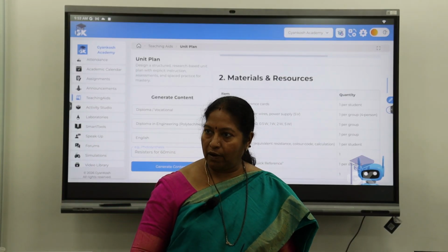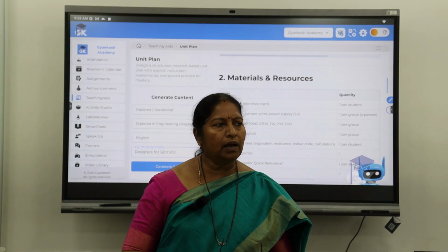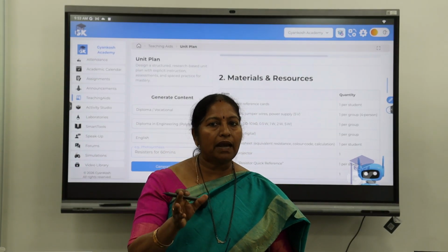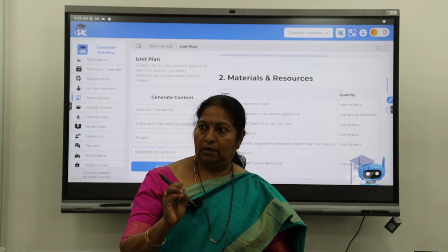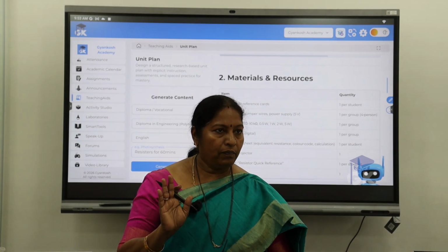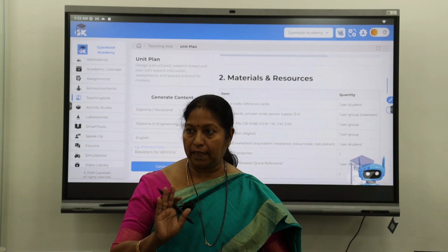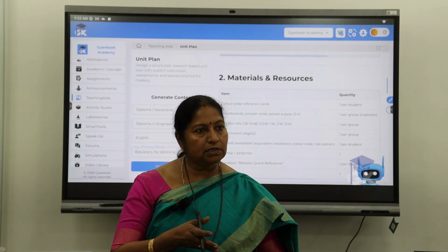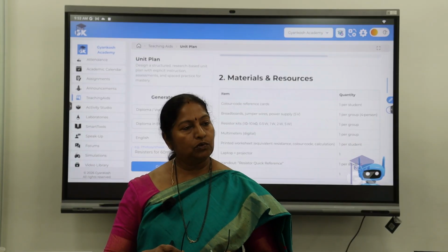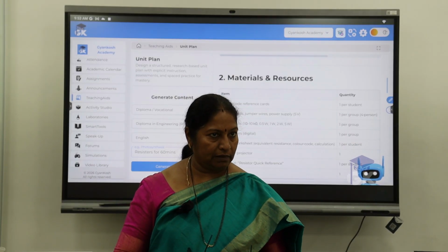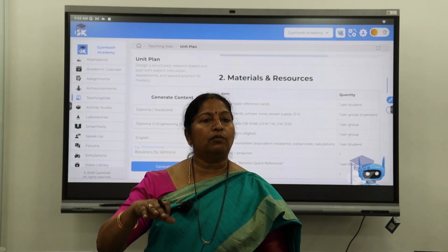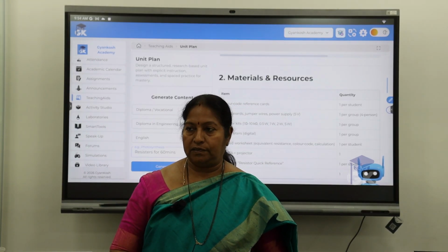Can I use a quarter watt resistor here? The quarter watt resistor can withstand the temperature of only 0.25 watts of power, not more than that, right? Now it is dropping about 1 watt of power. So if it has to withstand that temperature, I should use a resistor with more than 1 watt rating.